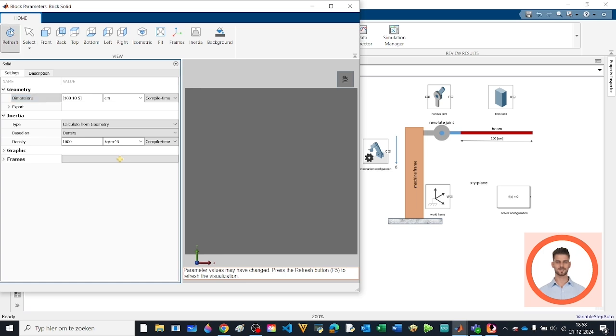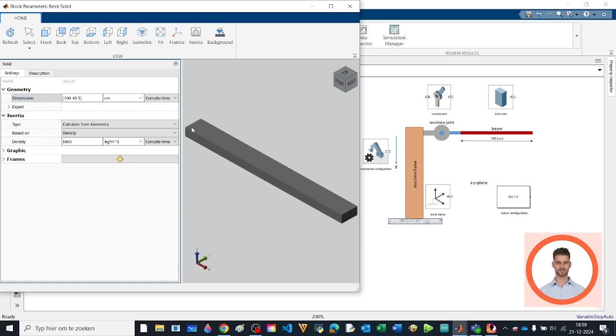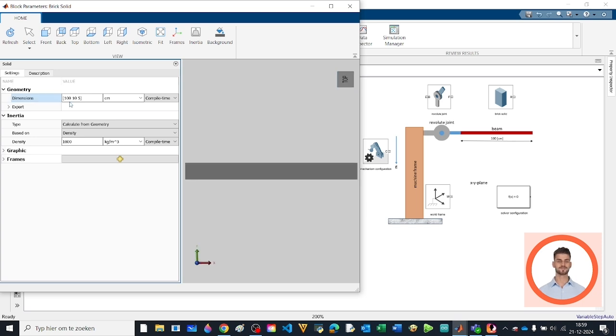The z-axis is perpendicular to the screen, and if the hinge is later attached to the left end of the beam, it will have the ability to rotate about it. Thus, the beam can rotate within the XY plane. Next, we need to set the mass of the aluminum beam by entering the density. The mass and mass moments of inertia are automatically calculated.